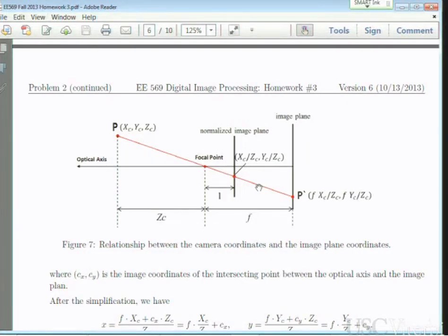So if you choose the wrong pixel density, sometimes you may not be able to see the whole 3D surface. The cube, maybe you only see just the middle part. If the pixel density is too small, then suddenly the whole projected image becomes too big, so you're not able to see, okay? So the ideal case is you adjust the pixel density so that you see the whole 3D surface or cube at about, say, 80% of the image.